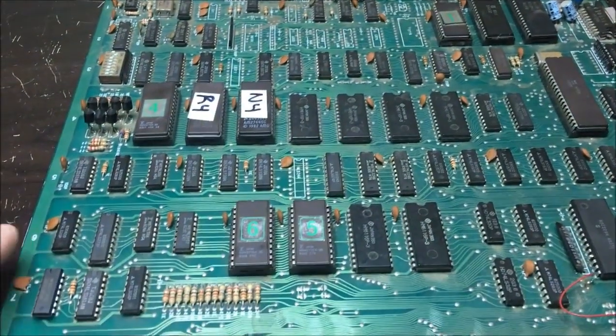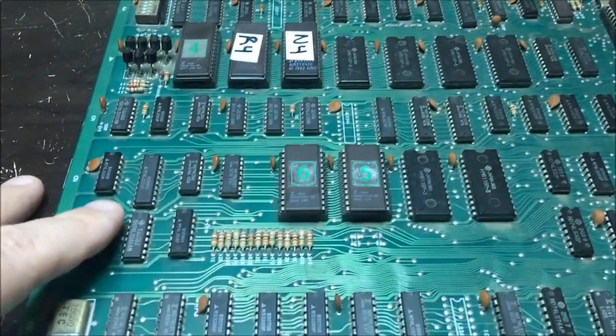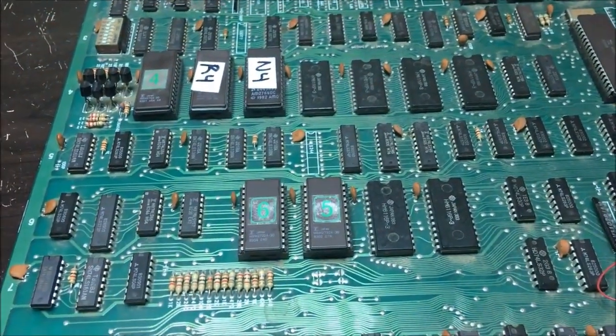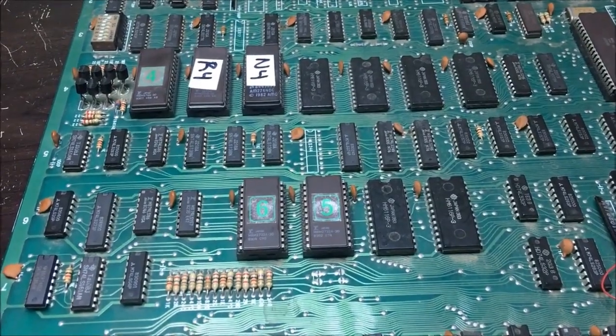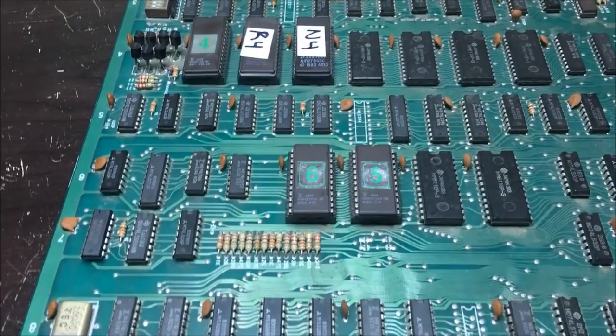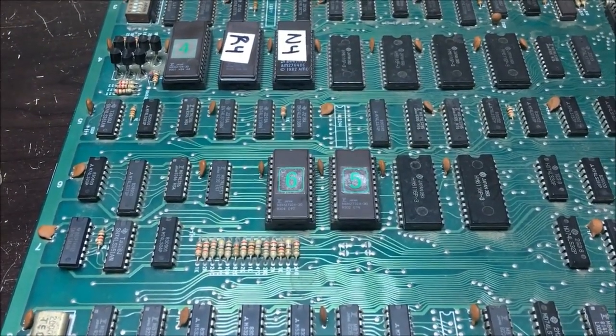And I now have video up on the screen, but it's not syncing. And one thing I've read, I've done some research on these bootleg boards, these Qbert bootleg boards, is that you have to invert the sync. So I'm gonna jump online and research this sync mod. It'll give me locations of where everything is, so I'm gonna go ahead and do that and get the sync flipped.